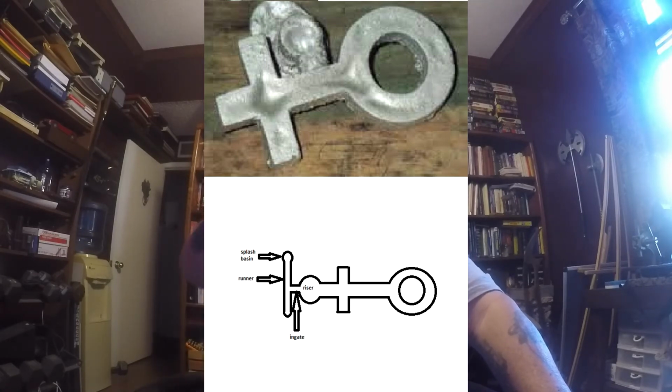Now, why would it have solidified at the circular portion first and not anywhere else? Well, because when that casting fills up totally, well, what do you have? You have that entire outer wall in contact with sand, and you have an inner wall that's in contact with sand, which hurries up the solidification of that metal. As you go up in the cross-shaped part of that, you only have the outside shape, the perimeter of that mold cavity, touching the sand.